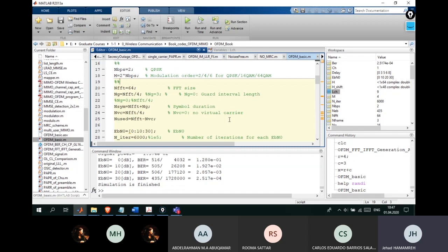You understand this point, yes? You have to make sure that the CP length is right. Here is your OFDM symbol, and this is the CP. The CP length, from the beginning till the end, should be greater than the delay spread of the channel. When the channel spreads, we want the spread to be contained within the CP duration of the OFDM symbol. If it exceeds, it causes interference to the data, and then your bit error rate will not be good and you will not be able to receive all the data successfully. So I believe this is also an important point to take into account.